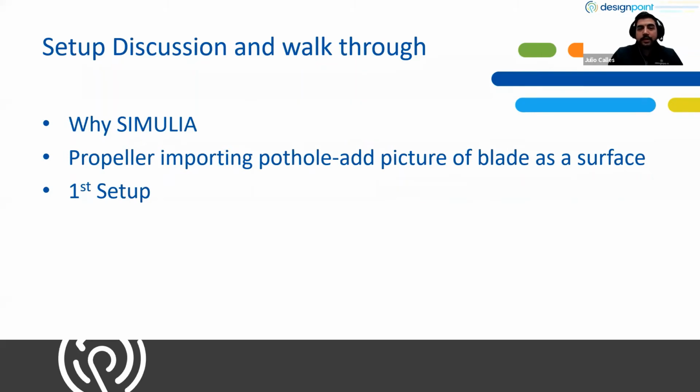Now, when you do a drop test analysis in SolidWorks Simulation, you notice one thing: you're only able to see one bounce of your model. And by that, what I mean is that you're only going to be able to see the results, the stresses, of what happens to your model at that very millisecond, or that couple of seconds, when your model hits the floor.